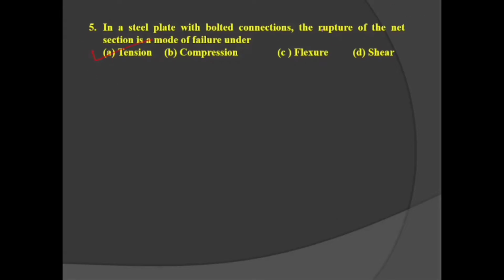Modulus of rupture, and you can also calculate the rupture strength, that is equal to fcr is equal to 0.7 times the square root of fck. fck is the characteristic strength of the concrete to be used. We have to check that particular section for the tension.